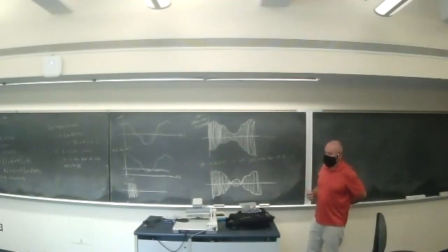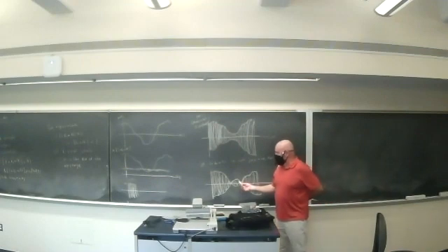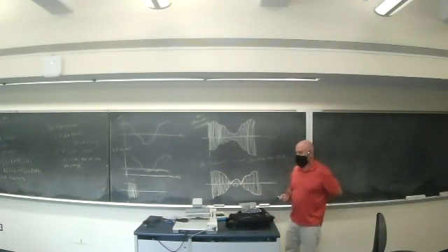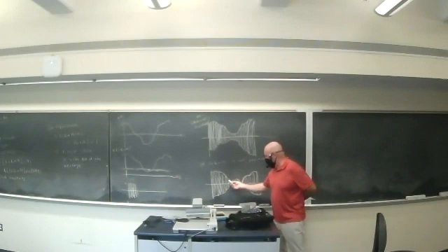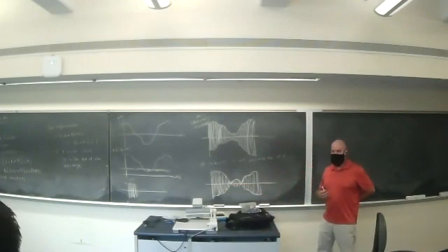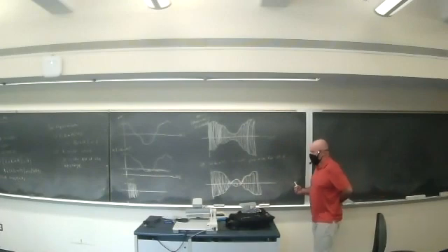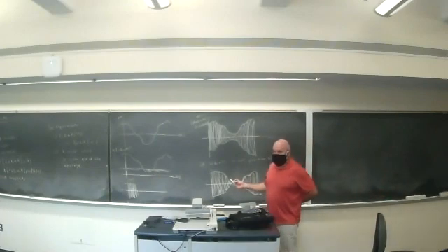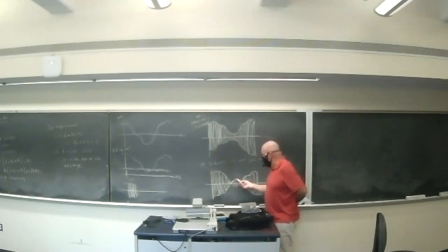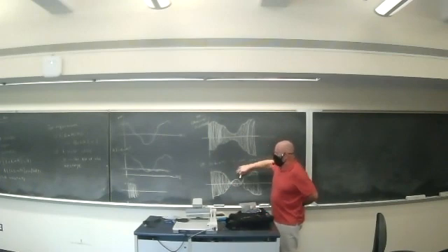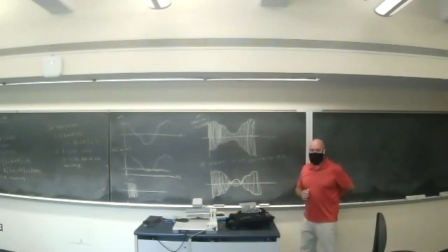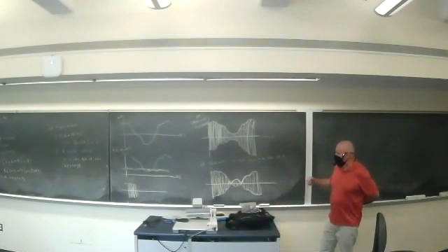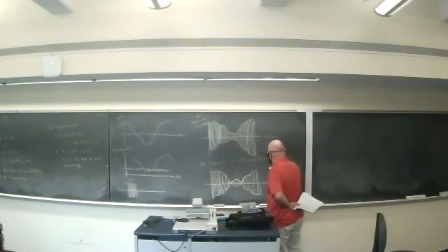Okay, and you might say, well, why don't I just follow the negative peaks? Our circuit won't do that. You won't know which is actually correct. We don't really know whether maybe the message really looked like this, okay, and had that positive. Or maybe in this case, it actually was supposed to go negative, but you don't know that. You don't know what the message looks like. Our circuit, it's called an envelope detector, will follow the positive peaks. This is a distorted version then of the original message. And so if this condition is not met, we get envelope distortion.